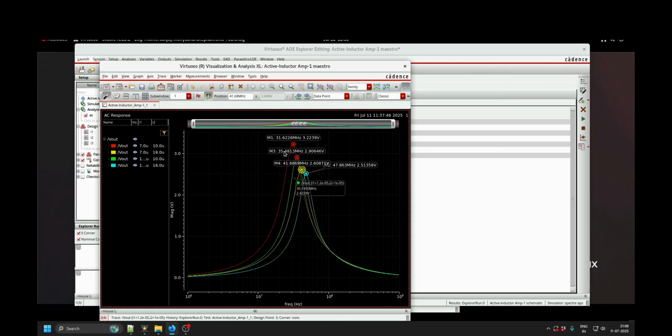Okay, and the range is generally from more than 2.5 to around 3.5, right? So it's good. The signal is getting amplified 2 to 3 times, in fact 2.5 to 3.5 times it is getting magnified. Only the desired frequency is getting magnified, and the Q is also much better. You would get a quality factor with a very sharp, small bandwidth, as compared to the normal spiral inductors. So these are the advantages.